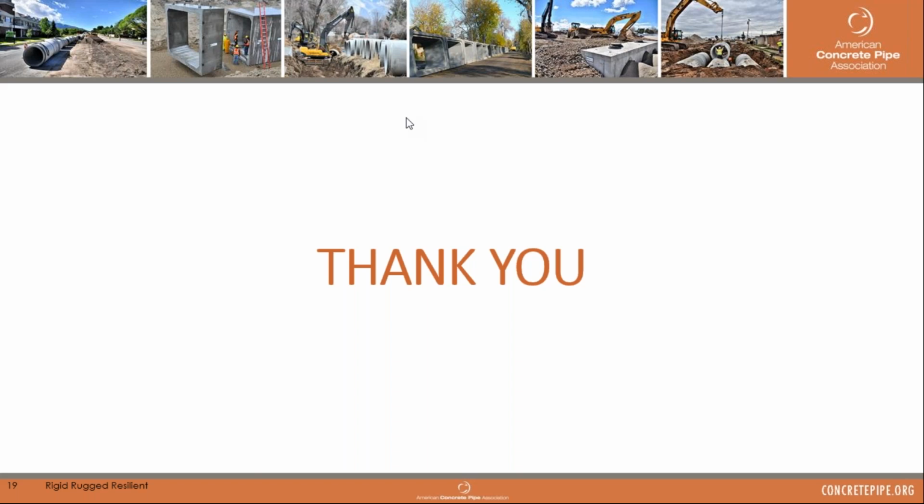Yeah, great. Thanks, Riley. I think you make a great point. Even the plastic pipe manufacturer would recommend a rubber or flexible booted connection to their pipe because there is going to be that deflection there, that movement where the structure itself will be much more rigid. Typically, it is a concrete structure, so just be aware that when you're making those connections that you're using proper connectors. Or if you're connecting a rigid to a rigid, you can actually use a grouted connection possibly. And so there is that as a difference.